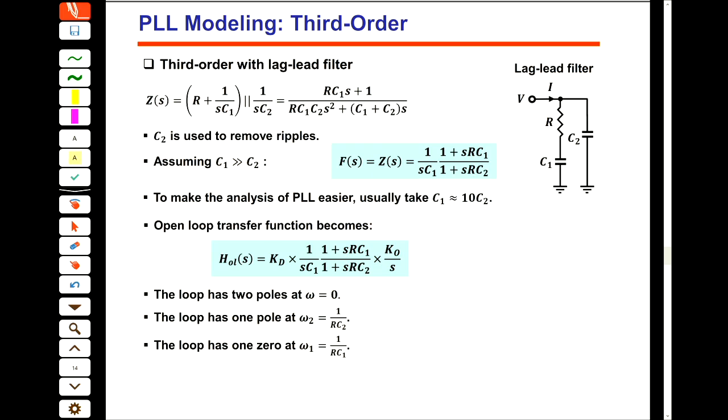Why didn't you do that? Because at the end it's anyway easier to calculate. Yeah, true, but you can, for example, write down instead of this a Z pi, and then calculate the value for Z pi. What's the value for it? It has a number, it's R pi in parallel with C pi. At the end of the day, put it there. I just want to confirm whether it's correct or not.